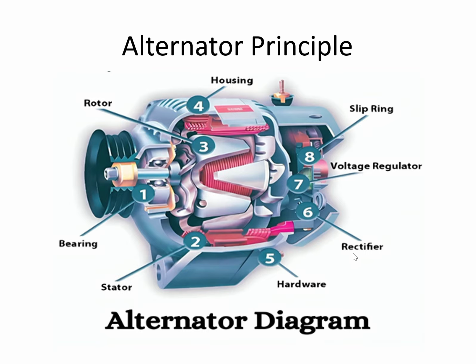Rectifier is used to convert that AC voltage into DC voltage, because in automotive vehicles, most of the loads are consuming DC supply only. So this AC voltage is converted into DC. Also, the main purpose of the alternator is to charge the battery. For battery charging, we need DC supply. So to convert the AC output to DC, we are using the rectifier.